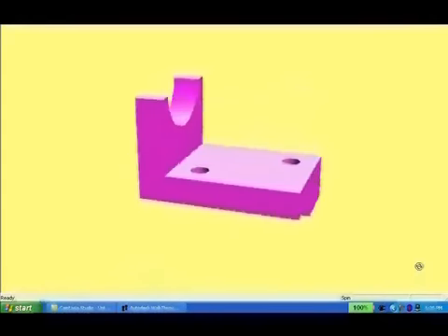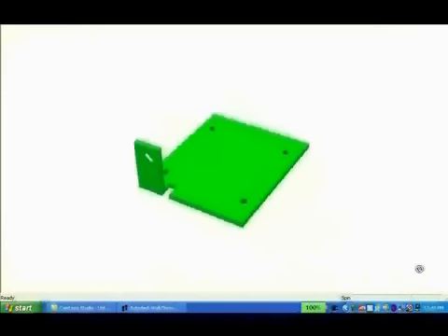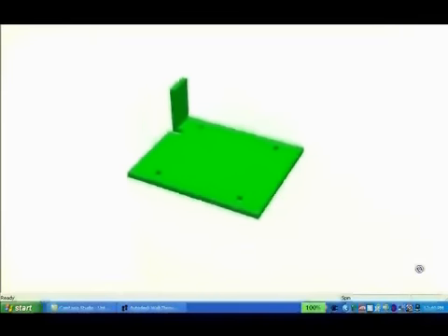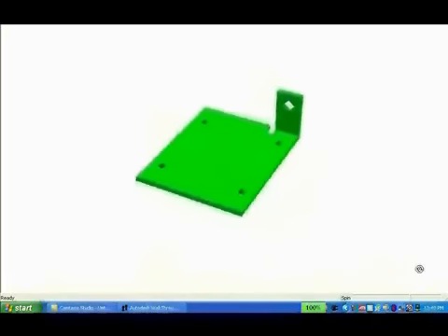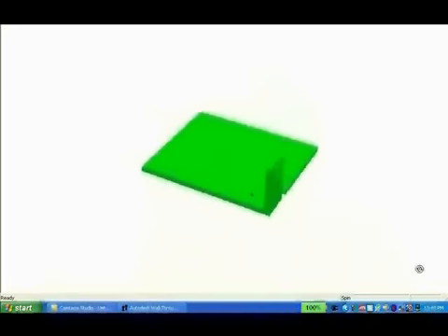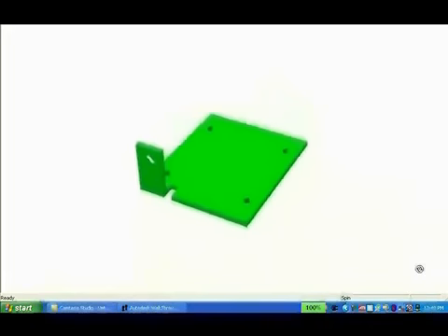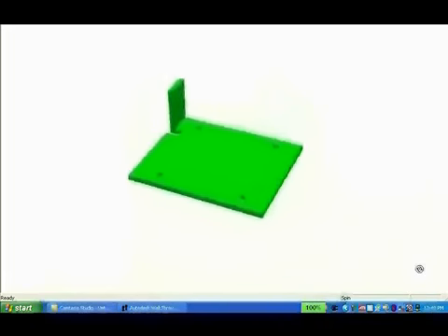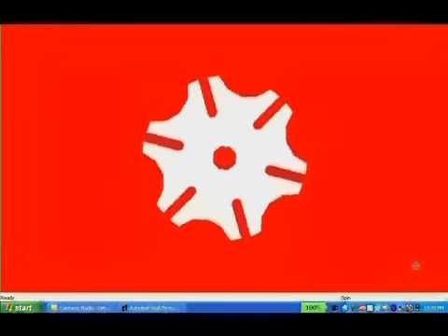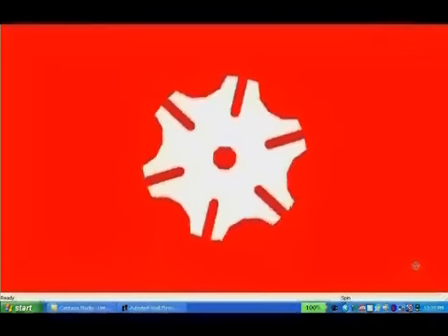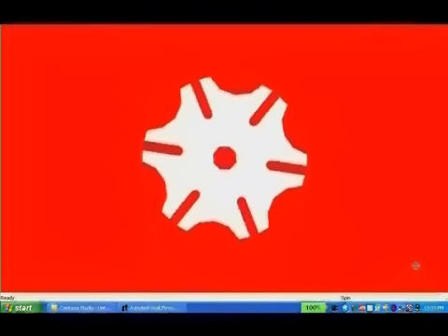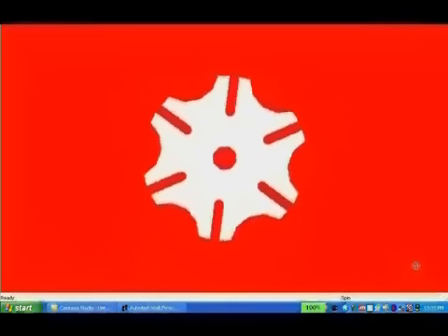Blocks are a useful tool also. Blocks are just groups of objects. A sample block might be a table or a chair. You can save that block outside the drawing file with its own .dwg designation. Blocks can then be inserted into any drawing as often as desired.